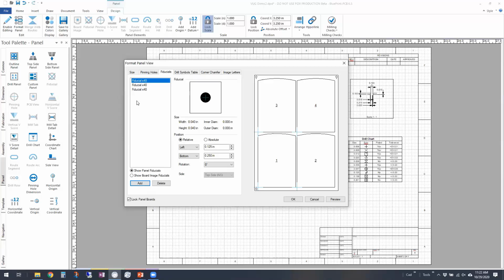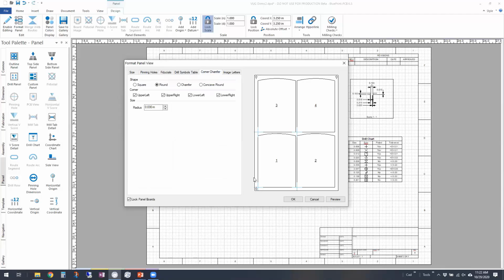They have a good document. They have the one-up Gerber. That's all they need to do a panel. I know I've done it for many years myself. Okay. Some other things that you can do here in the setup is you can round the corners of your panel, and then you can put that note that you see often on panel drawings, no sharp edges.